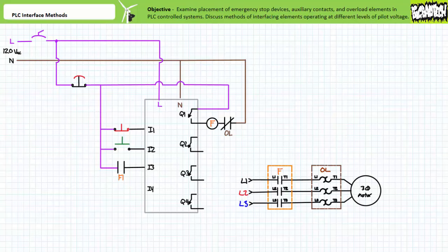We'll explore PLC-controlled motor starters in much greater detail in later lectures. However, for the purposes of this lecture, you should realize that by physically hardwiring the F contactor coil in series with the overload, the motor is protected from overloads without relying on the PLC. However, by incorporating the F1 auxiliary contact as a feedback input element, the PLC is made aware of the overload.